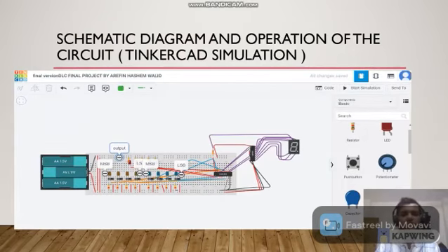This is the device we have designed using Tinkercad. At first, we added three 1.5 volt batteries, a total of 4.5 volts. Then we added 8 switches and 13 LED lights, then 13 resistors with 220 ohms resistance. We have used the 74HC283 adder to add two binary numbers in this device. This device will add two 4-digit binary numbers and will also convert the result to a decimal number. This is how a computer adds two numbers.